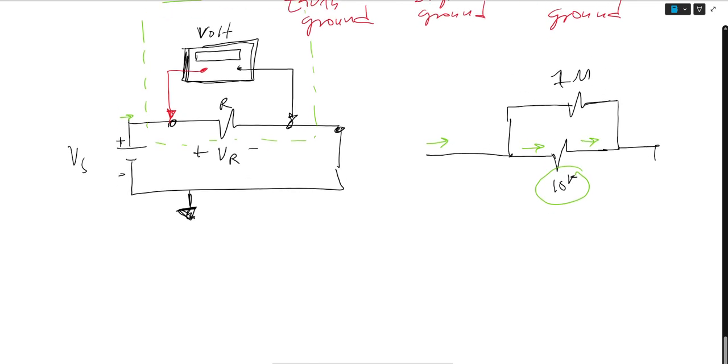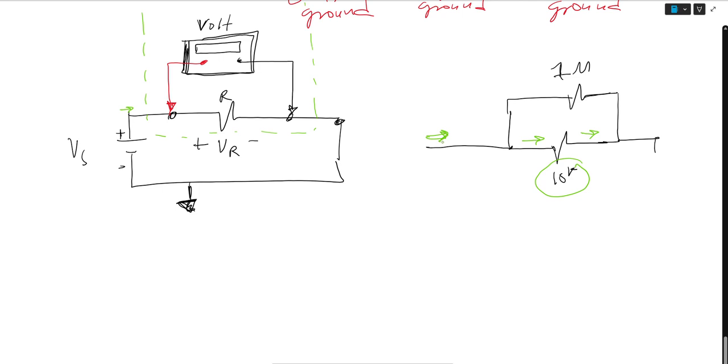Again, I think I made mention of this in the first lecture. It's like you're going to work and there's no traffic. There's the least amount of resistance on the side street versus a lot of traffic on the highway. You're going to take the side streets. So that's what the electrons do here. And this is something that goes into designing voltmeters: there will be some, a very, very, very small amount of current that goes through your 1 mega ohm resistor. But again, it's negligible compared to the current that flows to the resistor.